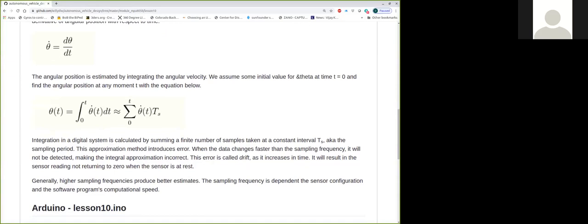And we've also learned that we get what's called drift error. Because when we bring this up and we calibrate it, we have a zero offset bias. And that zero offset bias, that DC bias, we try to calibrate and get rid of it, but some of that still exists. And as we sum these readings over time, we're summing in that bias and we're accumulating error. So that error is called drift.